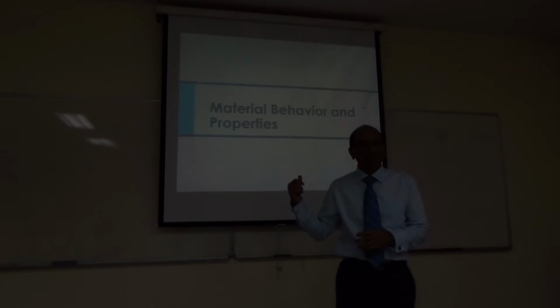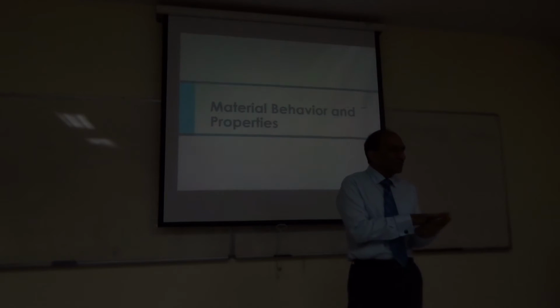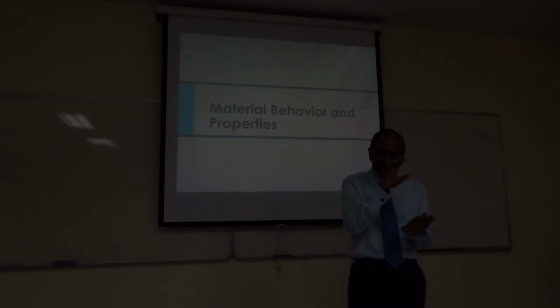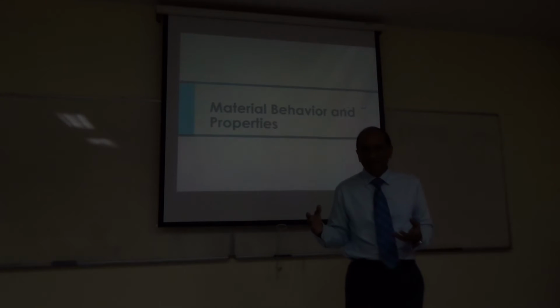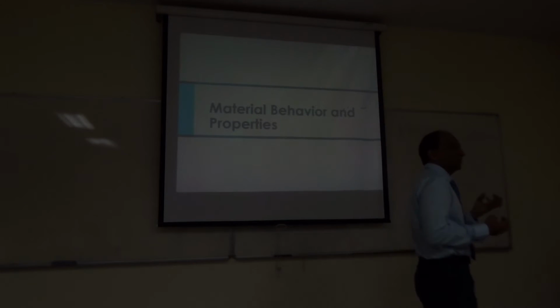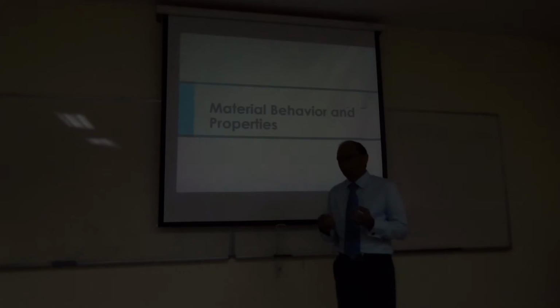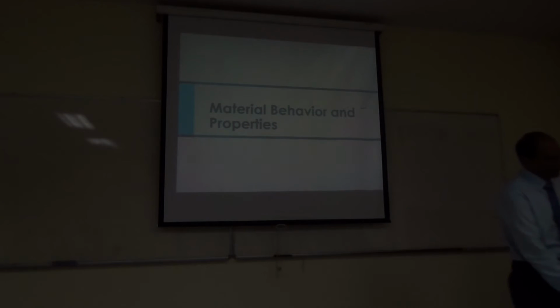Just now we already talked about it, stiffness, right? We are going to need stiffness for analysis, and for design, we are going to need strength. Two different things. For analysis, we are interested in stiffness, and for design, we are interested in strength because we want to control the response, we want to limit it. So limit is strength. So we are going to need these two very basic material properties somehow. They seem very simple, but as we will see, they are not.